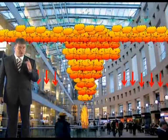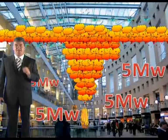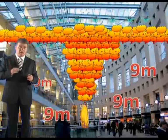Now sprinklers are only required in the atrium itself if the fire loading exceeds 5 megawatts or a 9 metre perimeter fire. So that's the key. If it's less than 5 megawatts, the design fire, or a perimeter of 9 metres, you don't have to put sprinklers in the mall itself. However, sprinklers are unlikely to operate in a very high atrium unless the fire is much larger. So even if you had a 5 megawatt fire, in a very, very high atrium the smoke getting up there is not going to be hot enough to operate the sprinklers anyway. So sometimes you can think, what's the point of having them? You've got to be careful when you put them in.